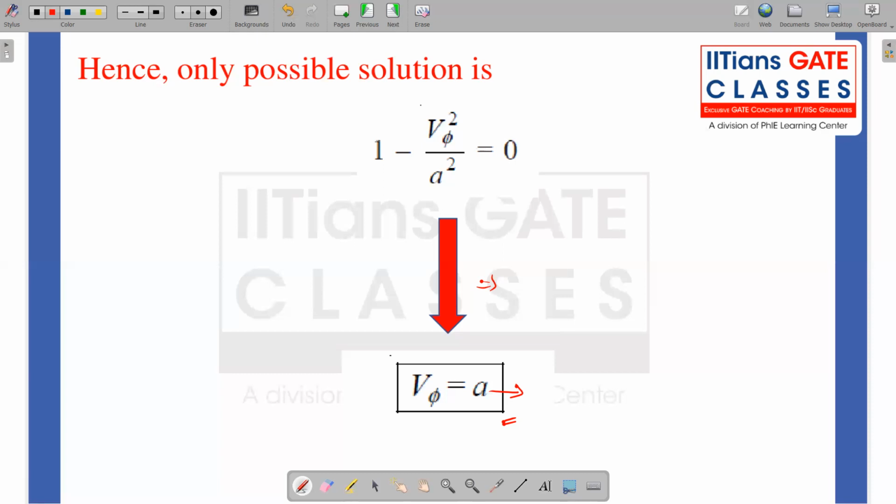So across the Mach wave, we already know that Mach lines are the limit of shock waves, where the properties change such that the total pressure is not lost, or we are not going to see an entropy increase. So the entropy stays constant. So that's a very important result from a physics point of view.